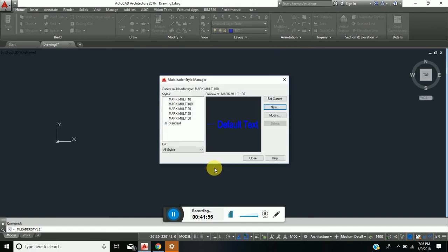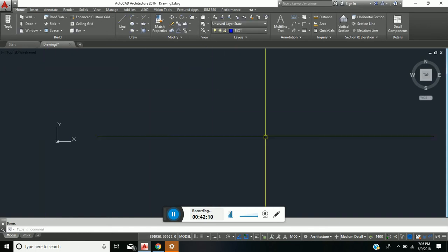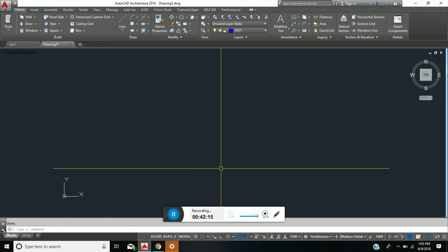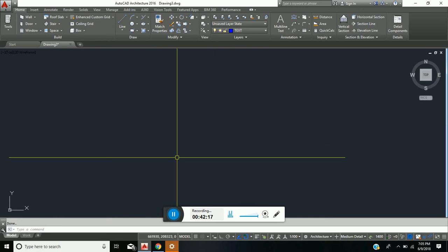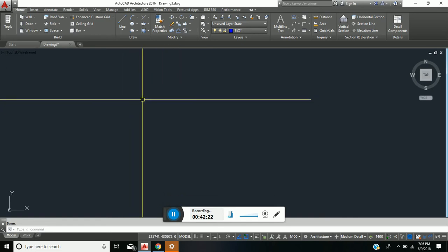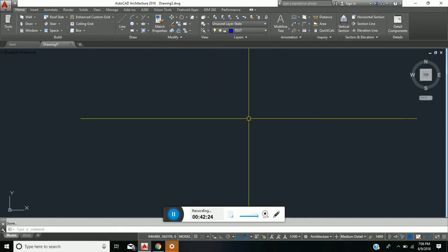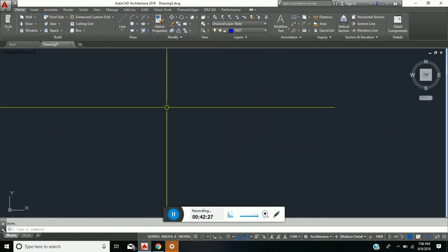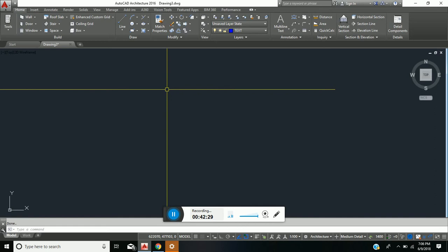Alright, here we have created all our text and dimension styles that will be used on our drawings. What we do now is there is no need to set any of them new, so we would give a close and we would have had our annotations basically set. What you want to do now is to save this such that whenever you reopen AutoCAD, you will now open AutoCAD from that template as opposed to having to go over the process. Alright, to do that,